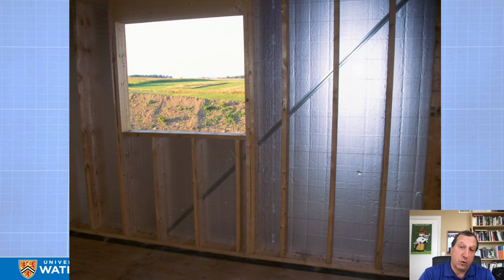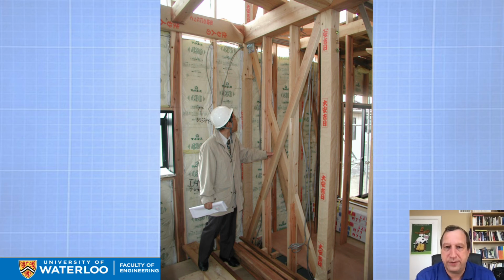Now, if the loads get higher, like I said, in multi-story buildings or significant seismic zones, or custom homes with large windows, like 5-meter wide windows, then we have to find other ways to get a structural bracing. And this is an example from Japan where, because of the seismic rules, they would quite commonly use wood diagonal bracing, even on a 2-story wood frame house, which is what this is.